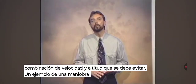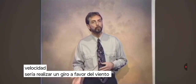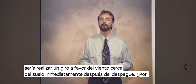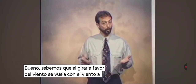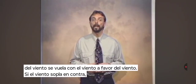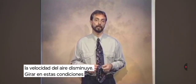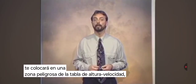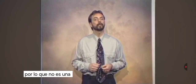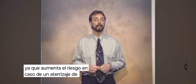An example of a maneuver that could get you into trouble with the height versus velocity chart would be making a downwind turn close to the ground immediately after takeoff. Why? Well, you know that when you turn downwind, you're going with the wind instead of into it. This causes the airspeed to decrease. Making a turn under these conditions will put you into a dangerous airspeed-altitude region of the height-velocity chart. Therefore, it's not a good practice because it increases the hazard involved should an emergency landing become necessary.